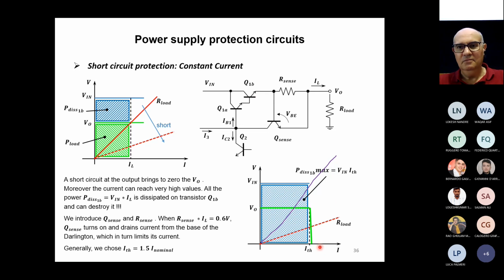Okay, so our system is in a short circuit situation. Anyway, the series pass transistor is designed to survive this situation. When we realize what is the problem, maybe it's the load that is short circuit, maybe it was the famous screwdriver fallen on our circuit, we remove the screwdriver and the system will start working again, because we have not destroyed the series pass transistor. Okay. So this is a very simple and important circuit that is used almost everywhere for limiting the maximum current.